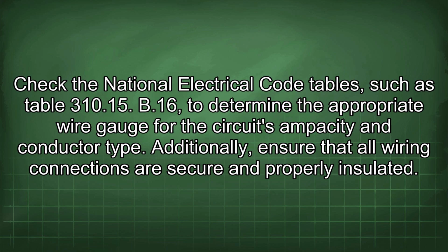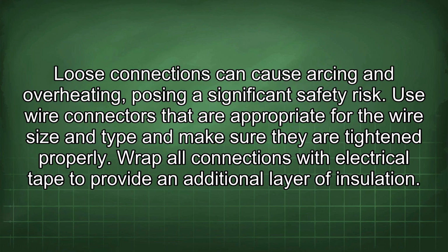ampacity and conductor type. Additionally, ensure that all wiring connections are secure and properly insulated. Loose connections can cause arcing and overheating, posing a significant safety risk. Use wire connectors that are appropriate for the wire size and type and make sure they are tightened properly. Wrap all connections with electrical tape to provide an additional layer of insulation.